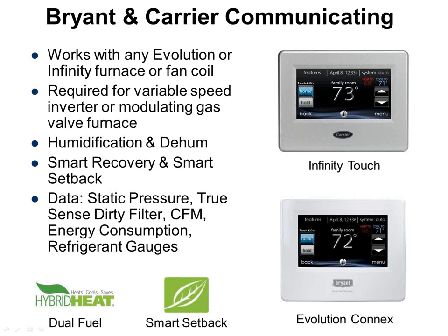If you have a communicating piece of equipment, especially modulating gas or modulating compressors, you really want to use these stats. It does the humidification and dehumidification sequences like you would expect of a high-end stat. It has smart recovery, which, by the way, pretty much all the stats we're going to talk about today have. They all call it something different: smart recovery, intelligent recovery, adaptive start, optimal start. Basically, it means if I tell your stat to go occupied at 8 o'clock in the morning, it's going to start tweaking set points at 7-something to get us to the exact number at 8 o'clock. It'll calculate how early it needs to start in order to do that based on previous days' worth of run history.